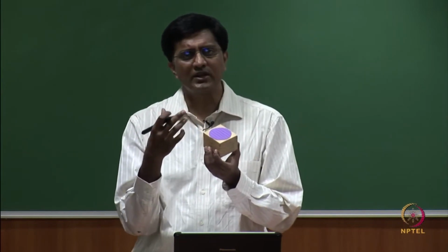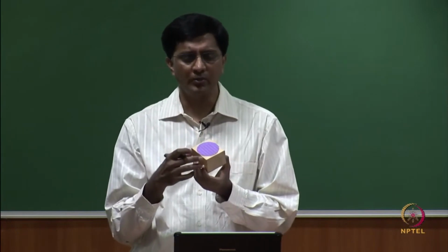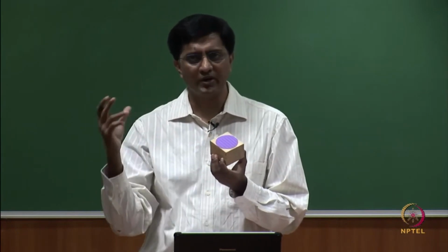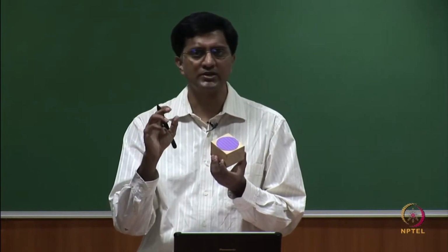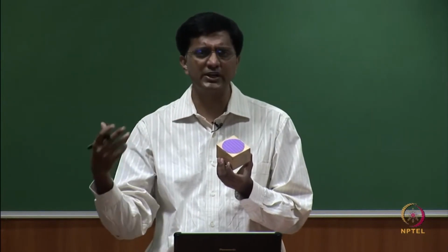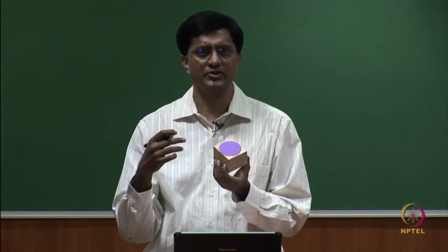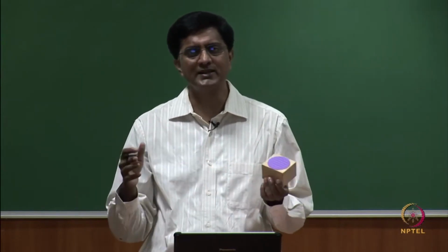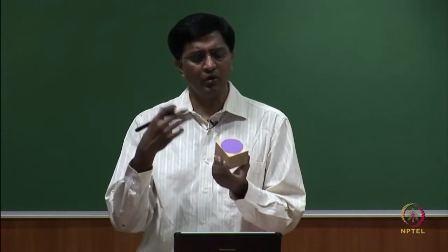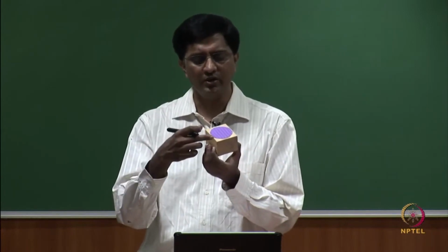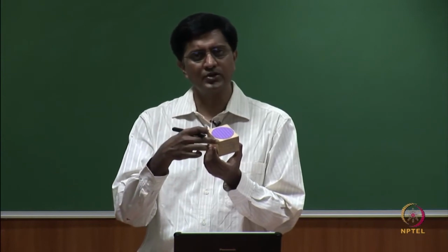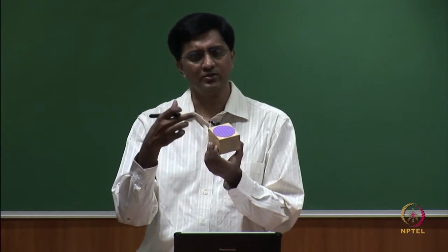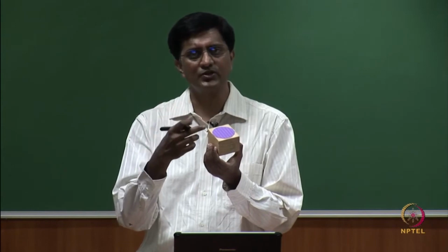Then this gives us a little difficulty in drawing, because you always need to multiply your dimensions with the scaling factor 0.816, and then it becomes a very tedious job to depict this isometric view. So, to make things easy, though we realize that this is foreshortened, we ignore the point and use the true length.